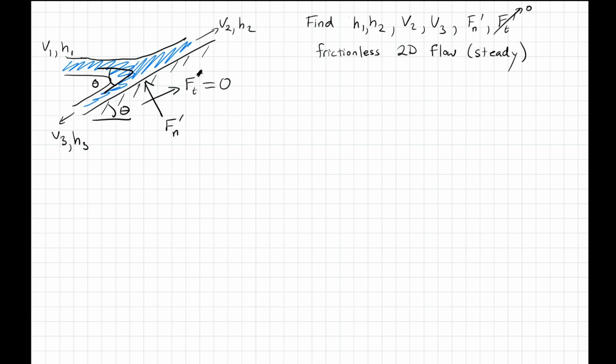Okay, so just as a reminder, we solved part of this already. So we employed mass conservation to find that, or Bernoulli's equation. So we applied Bernoulli's equation first, actually. So Bernoulli's equation along a streamline that goes from the incoming jet to either the point 2 or point 3 will tell you that V1 is actually equal to V2 and V3.